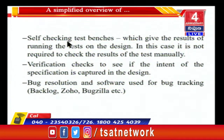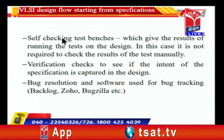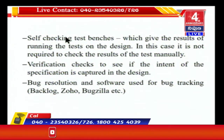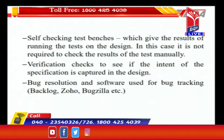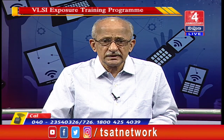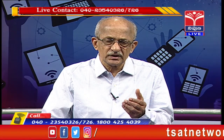And from those values, you apply your own judgment and tell whether these are expected values or not. Whatever you can do mentally sitting there in front of the terminal can also be done using logic in the test bench, in such a way that the test bench itself determines whether the output obtained from the design is correct or not. Now, to do that, you need to compare this output with the expected output.